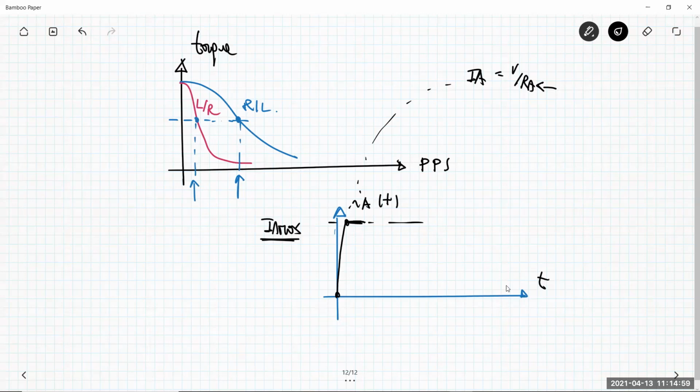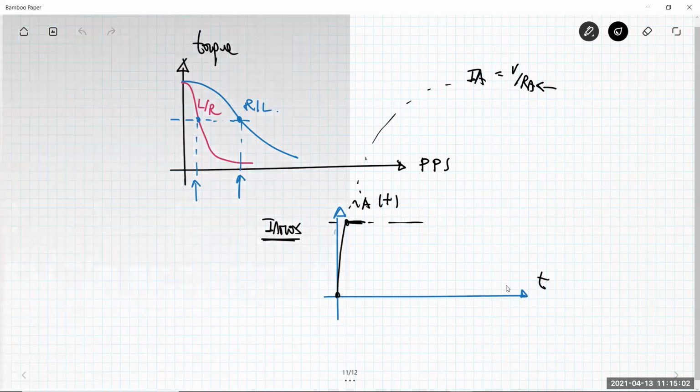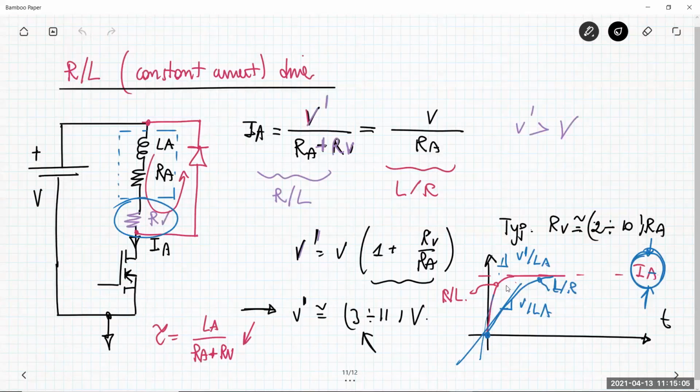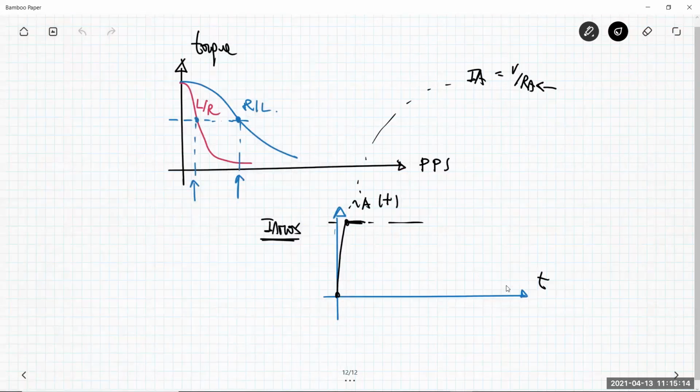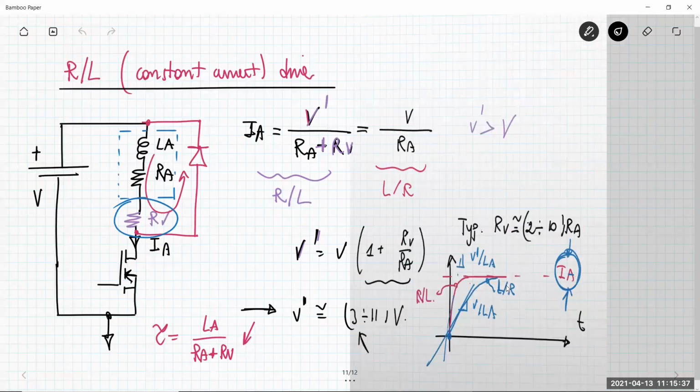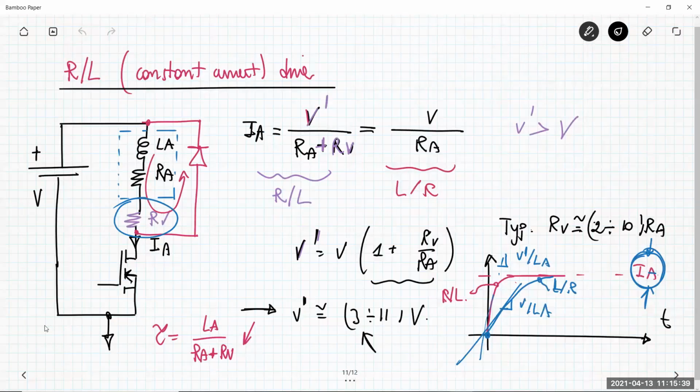So first of all, I want to say I employed a different strategy for the turn on. Not waiting for the transient to end, but including something more that understands the maximum current that I have in the phase. This is separate: choosing the voltage from the current level. I have to decouple these two parameters, the voltage V and the nominal current, and this can be a good choice. The second problem is that I also have to accelerate the turn off.